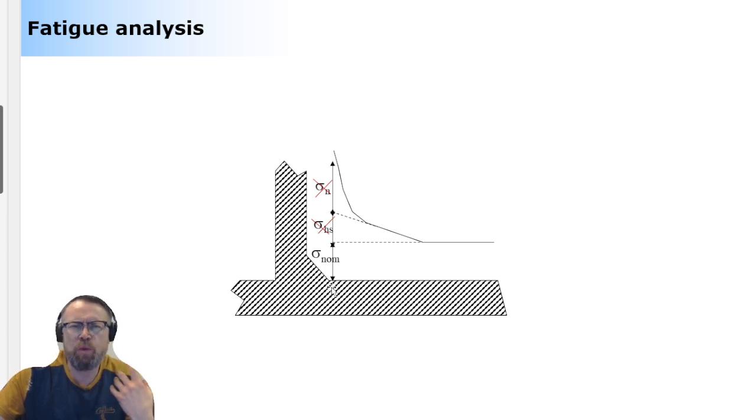When you look carefully, locally, and keep in mind this is a very, very local thing that I'm explaining here, in the area where the crack is propagating, where the initial crack is located, there are high residual stresses. Residual stress is because of the amount of heat introduced during the welding process.